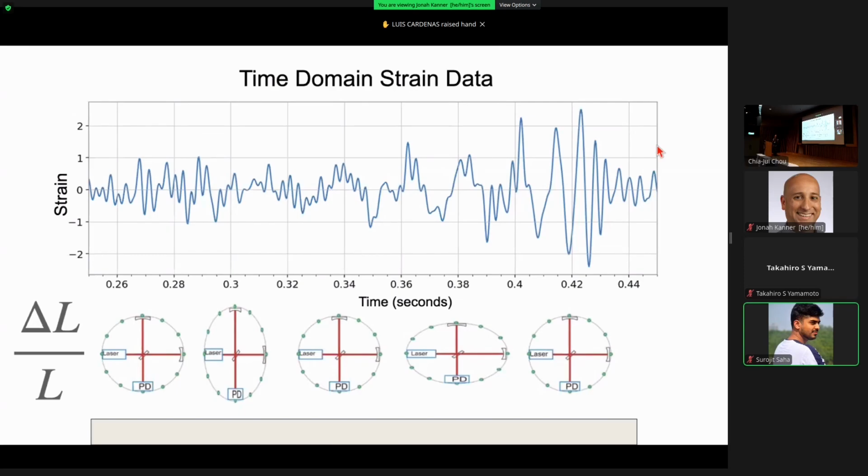It's not as simple as opening a file and boop, there's the signal. Instead you open a file and what you find is a bunch of noise, and then there's some number of processing steps to be able to find the signal. So what we're going to do over the next few days is introduce you to the types of processing that take you from a raw data file to actually finding a signal. That'll include some basic signal processing, things like whitening and bandpass filtering. It can also include matched filter searches, which of course are the most sensitive way to search for signals in a large amount of noise. And we'll try to cover all of that here in the next few days.